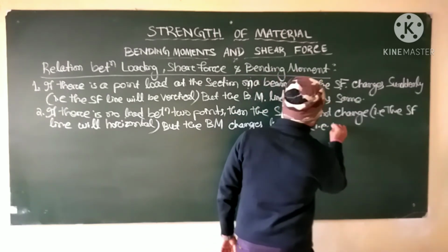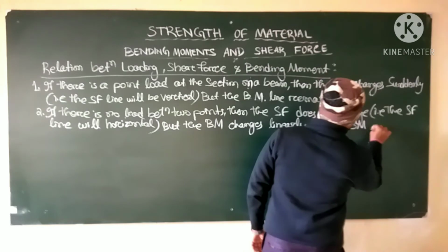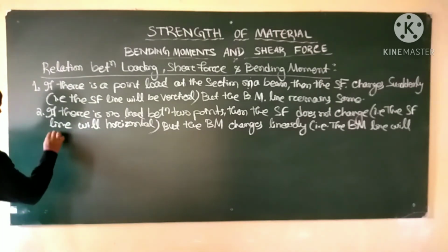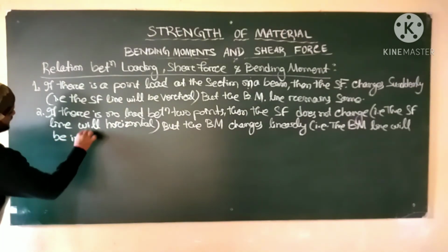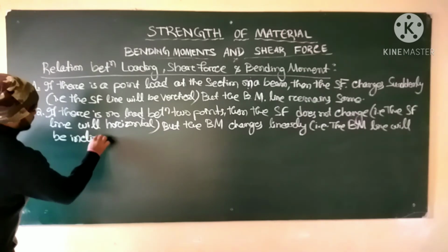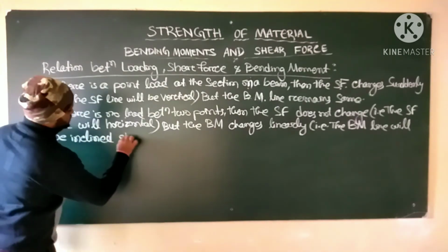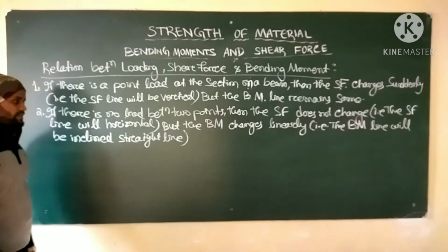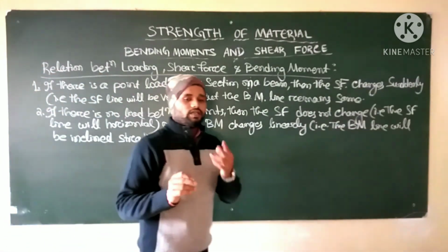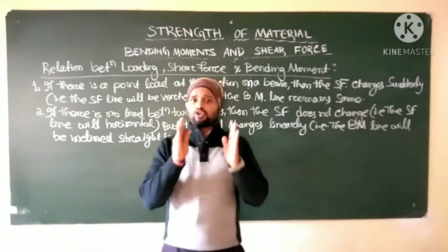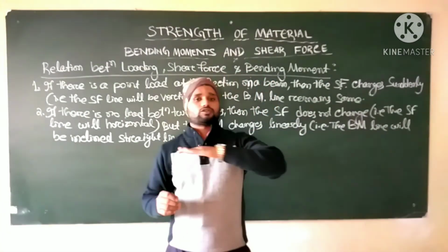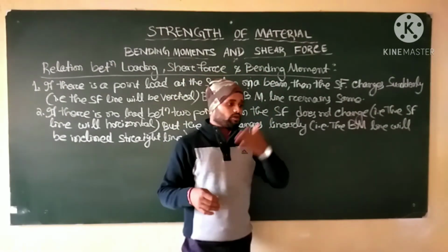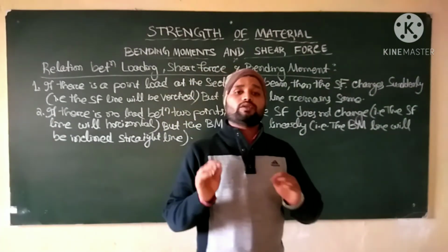That is, the bending moment line will be an inclined straight line. So in the no load condition, if there is no load between 2 points, then the shear force does not change, but the bending moment changes linearly. When we solve many problems, we will see what happens.